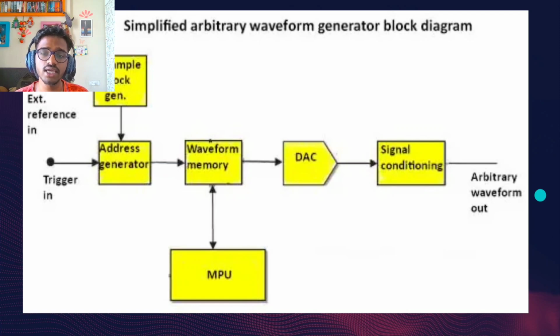Users can compensate for Nyquist zones, define LO frequency, and specify bandwidth. High-speed serial facilitates signal creation and jitter simulations for design validation, margin characterization and conformance testing. Capabilities include jitter generation, spread spectrum clocking, pre-emphasis, and noise addition. Multitone and chirp, useful for military, aerospace, and RF applications, allows the creation of tones and chirps with specified frequency and characteristics. Optical simplifies the creation of modulated optical signals for high-speed telecommunication networks supporting various modulation formats.